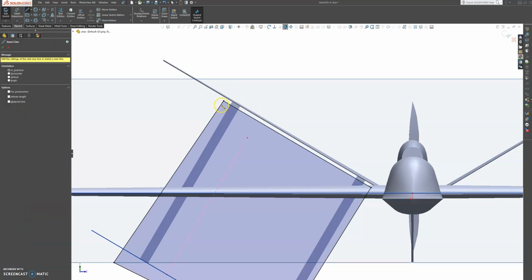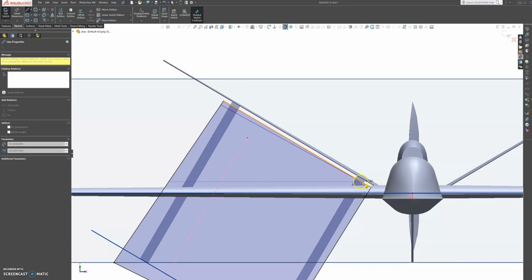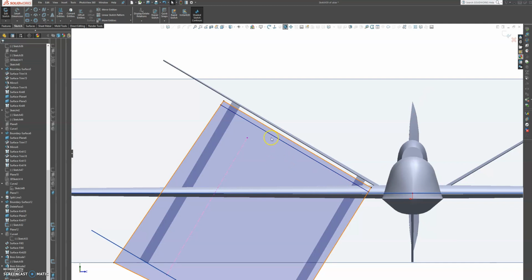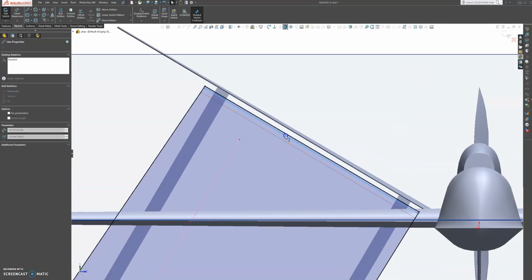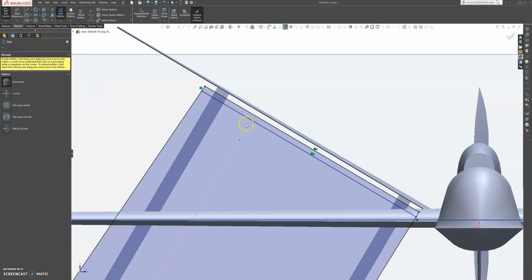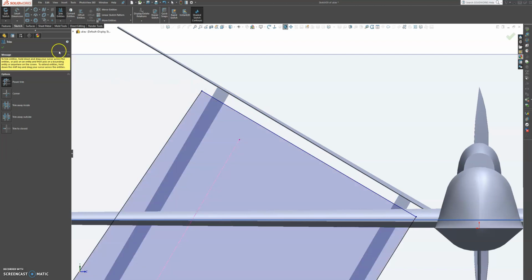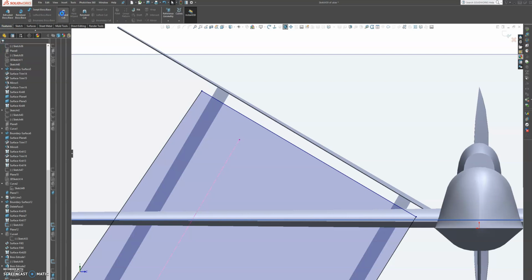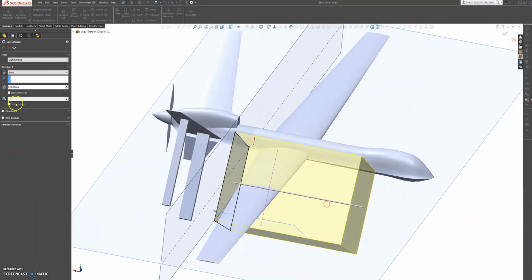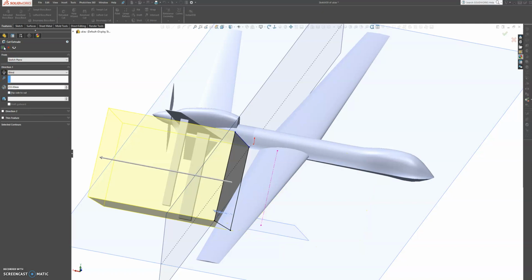Instead, let's add a sketch here. Let's be parallel to that one. Okay, and we don't want to leave too much this time. We don't want to take away too much and leave too much. So to make it square, something like that. Okay, and just cut the top part off. Cut this edge, this end. Okay, features, cut extrude. Remove that around. Press OK.